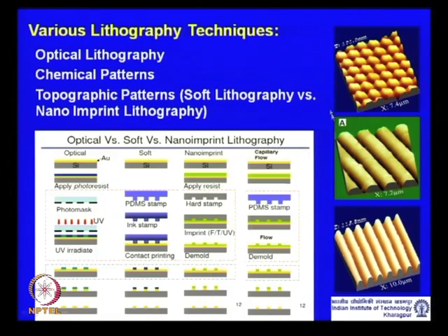And the fourth technique, the molding mode technique that we are going to discuss today, is pretty similar to NIL, but you do not really go in for thermal processing, or you do not use a rigid or hard stamp, and typically your pattern replication is not by viscoplastic deformation, but is triggered by a capillary driven flow, and the final result is very much the same as NIL.